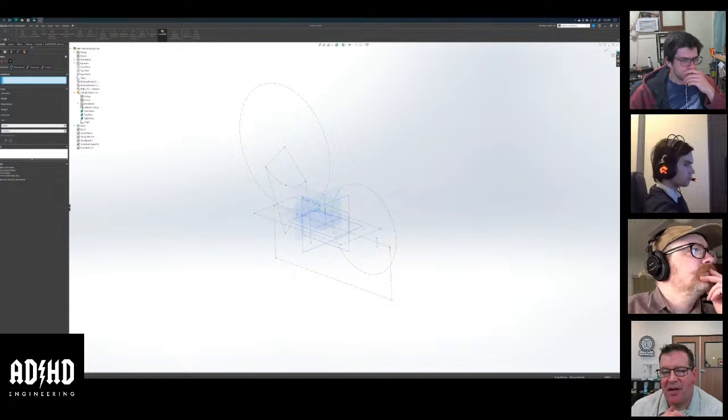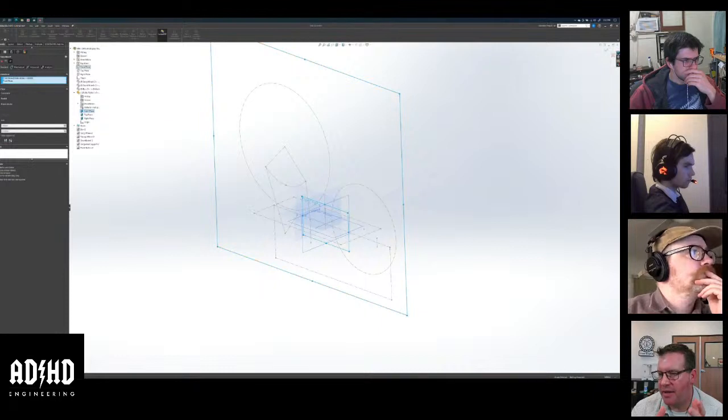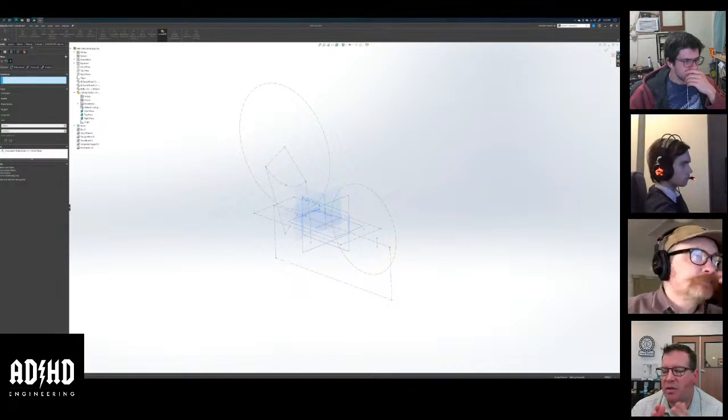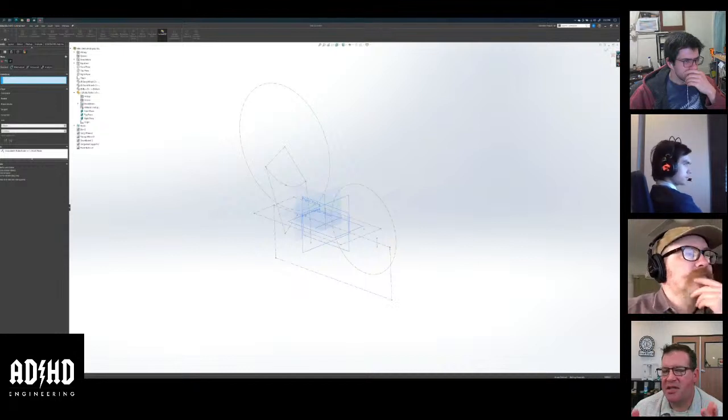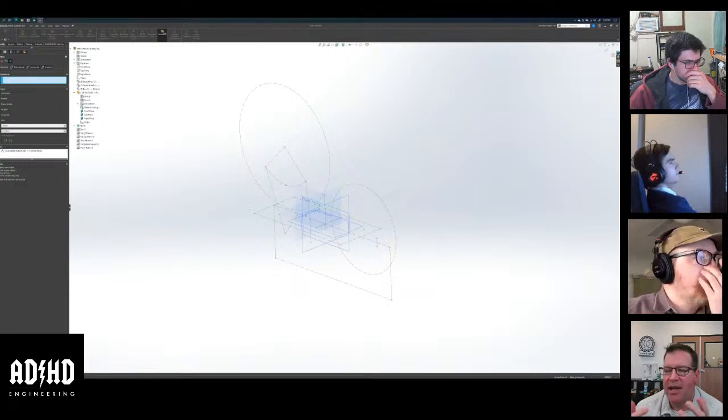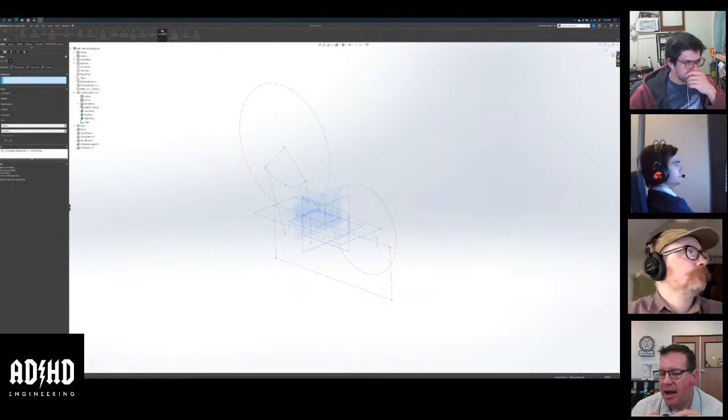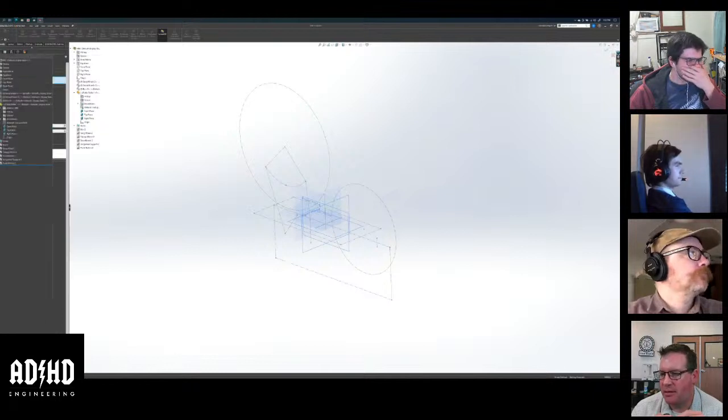So I think I just figured out. If you're actually designing a part with the assembly context open around it, right? Then starting it already fixed, which seems like a dumb way to mate things, actually makes sense because you're designing it in situ, right? Exactly. You wouldn't want something fixed if you're bringing in a part that was already designed from the outside. That's very true. So in this context, having things be fixed, I've always thought, oh, it's fixed, that's just a cheap way of fixing it. Well, if you're designing it in this assembly, having it start fixed as default makes a lot of sense.